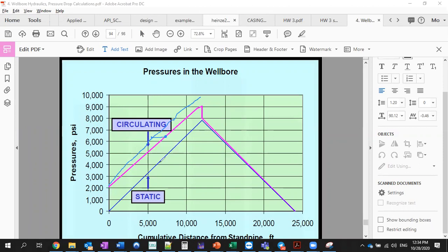Okay, so what you need to do, just a summary here, at any depth, you need to calculate your hydrostatic pressure, right? So let me look at 5,000 psi. This is your hydrostatic pressure, right? And you would add basically your pump pressure, of course, right? How much is your pump pressure? 2,000. Sorry, I thought this is the depths, but I should go vertically. So this is not correct.